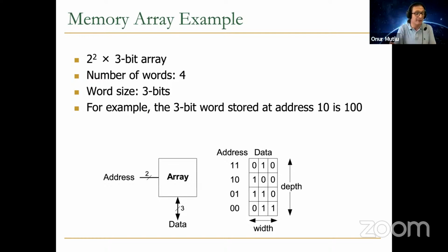As a result, your data width is usually small, let's say 64 bits, for example, or 8 bits. So if your array row size is 8 kilobytes, you need to select the 64 bits from the appropriate column based on a column address. We will see this in a little bit also, but this is important to keep in mind. That's why we size the arrays to maximize capacity while getting acceptable latency.